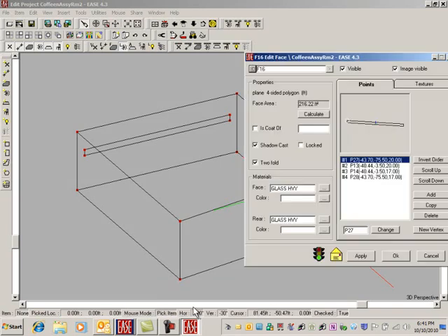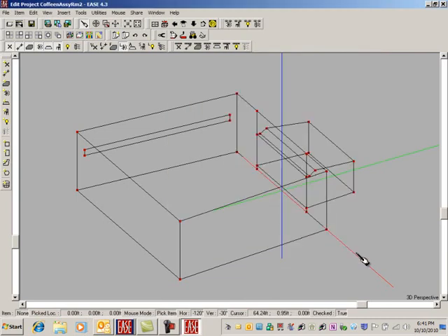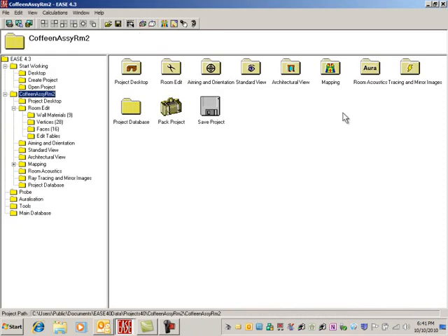Do I want to minimize all base files? No, because I want to include all of the wall stuff that I put in there, not just what I used. I'll take that check mark out. Include cluster components. We have none, so it doesn't make any difference. I could have a zip file here or just a PPJ file, which either one's all right. I'll make a PPJ file, just say OK. And this tells me what I did.